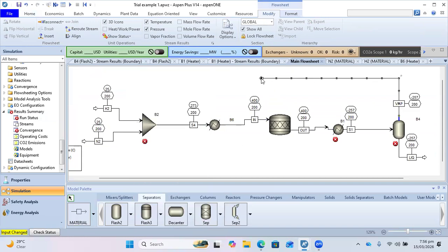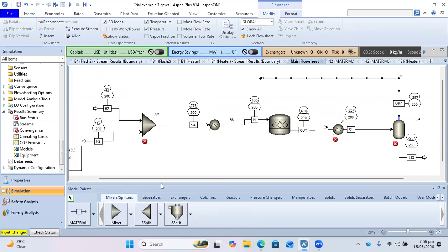So we all know what a purge stream is, right? From chemical process calculations. Please, are we all familiar with what a purge is? Okay. If we are talking about a purge stream, we are saying that we have a stream that would remove some amount of the material from the main stream. Instead of sending everything back, we'll just remove some amount of it and then we can maybe flare it, send it to a different section, anything of that sort.